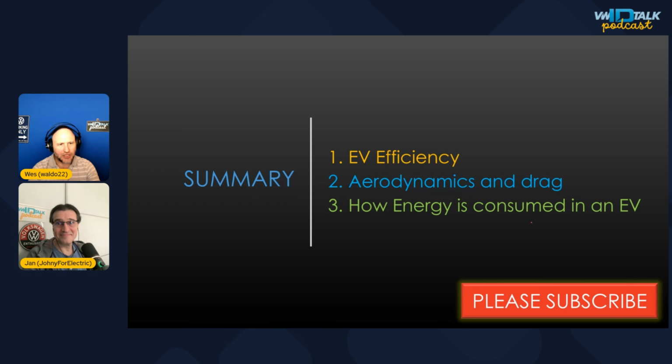The second thing is, what can you do to increase your own efficiency? Well, don't drive 75 miles an hour. If you can drive 65 safely, then you should do that instead. That's to keep it under 100 kilometers an hour, or 60 to 65 miles an hour. And that should really help your range. And then the last thing is, in the winter, see if you can heat yourself with your seat heater and not run the battery or the cabin heater, if you can help it. It's all those things together that can really make a difference.